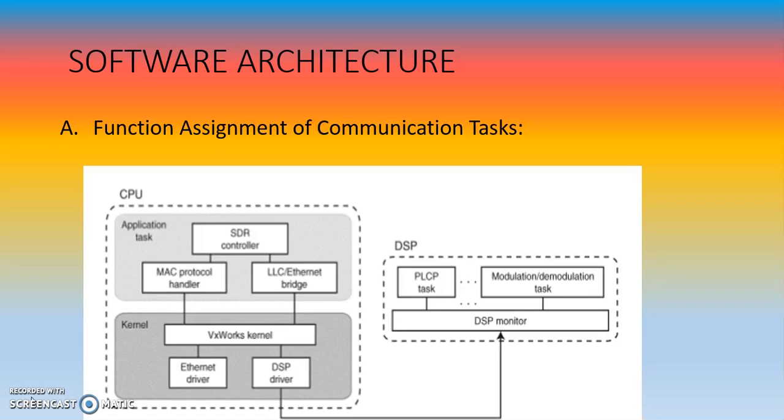Software architecture: the hybrid programmable architecture of a CPU, DSP and PPP enables more flexible task assignment, but the arrangement affects system performance seriously. This section will also describe the architecture of software assignment to each processor in WLAN mode and the SIFS issue, which is the most difficult problem when implementing IEEE 802.11 WLAN on this architecture.